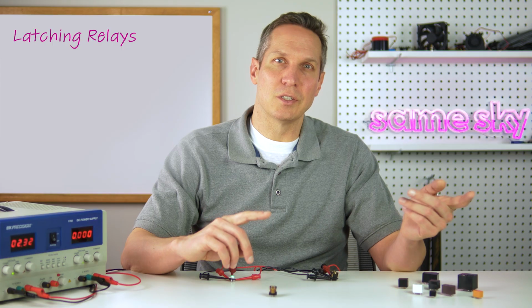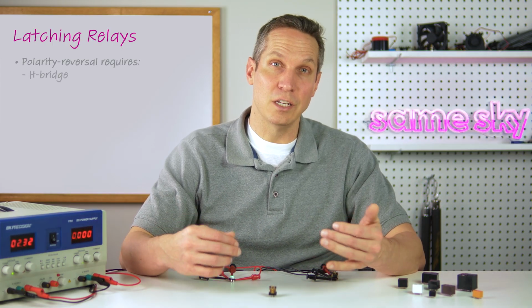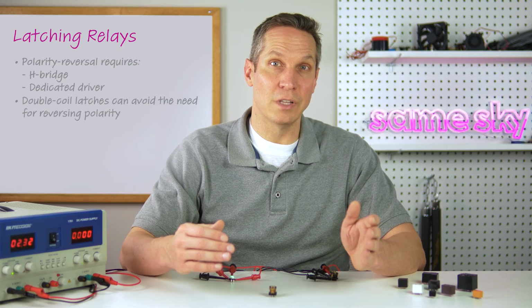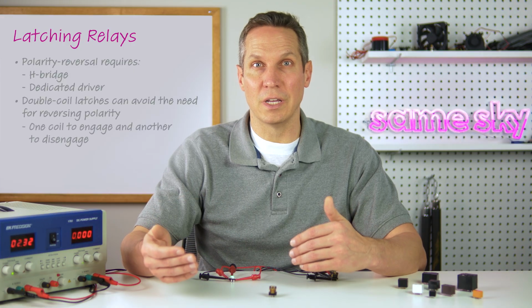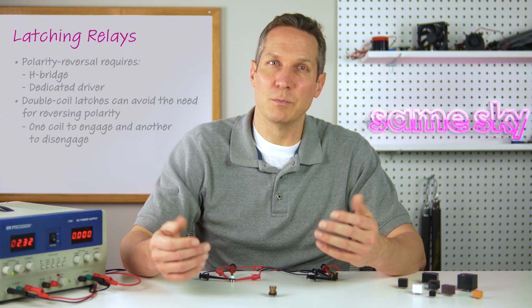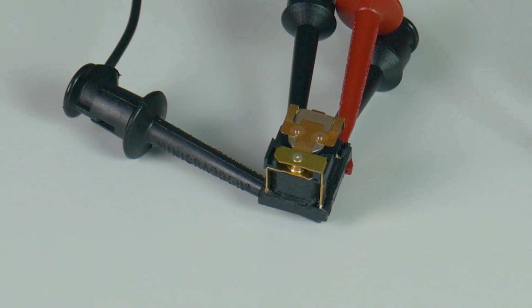Applying pulses in the opposite direction means a polarity reversal in the driving circuitry, requiring an H-bridge or a dedicated driver. This can be avoided with double coil latching relays, with one coil to engage and the other coil to disengage, but the driving circuit would still be slightly more complex than a non-latching relay. I actually have two small working examples of a non-latching relay here on the desk.